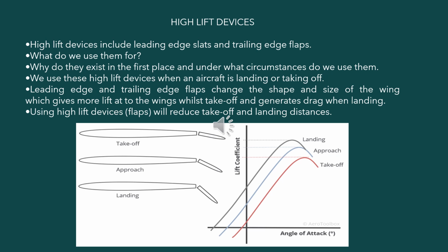So here in this slide, I am going to discuss the leading edge flaps and trailing edge flaps. Slats and flaps are high lift devices that are intended to produce maximum lift coefficients on aerodynamically designed wings of aircraft. These trailing edge flaps and leading edge flaps increase the wing lift and decrease stall speed during takeoff, approach, and landing. These are normally operated with hydraulic power from the left hydraulic system,